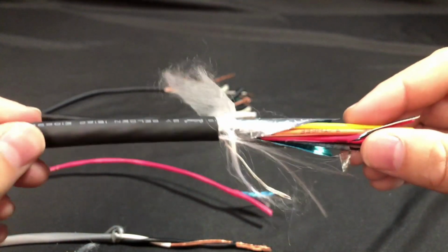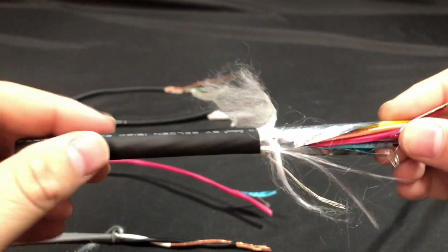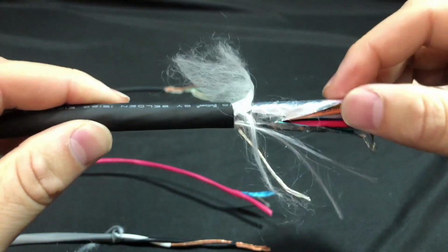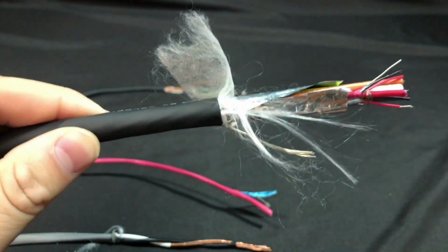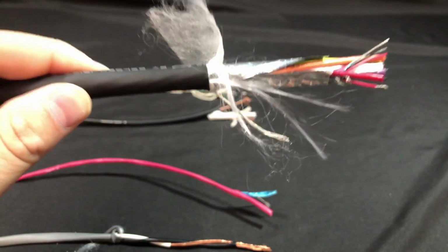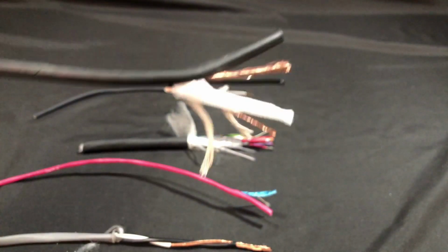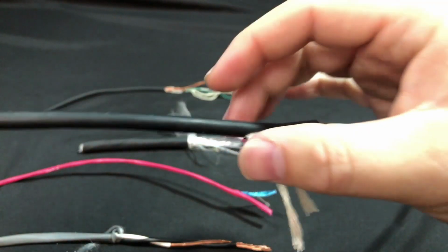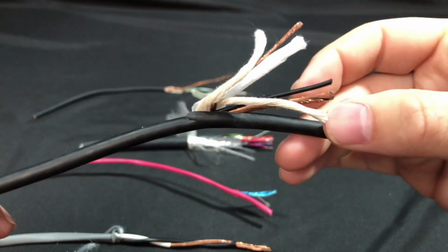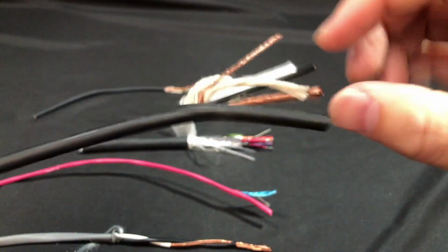One of the cons of foil is its durability is low. Just like with a paper clip, if you bend it back and forth a lot, eventually it's going to break. The same thing with foil, and then its effectiveness in shielding goes down, and so it's not as flexible. A braid doesn't have that problem, but it takes up much more room. So with braid, you can bend back and forth, it has a lot more flexibility, but it's not good against radio frequency interference, just against electromagnetic interference.